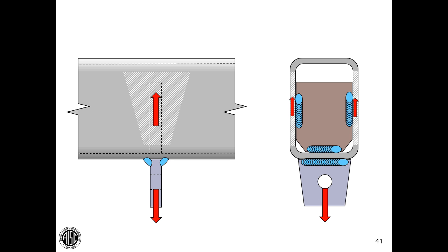Now, I recognize that you can't do this in every configuration. The diaphragm has to be near the end of the tube so I can get it in place and weld it in place. But I hope you can see that now we've created a very effective load path for that vertical load to enter into the member that lies parallel.